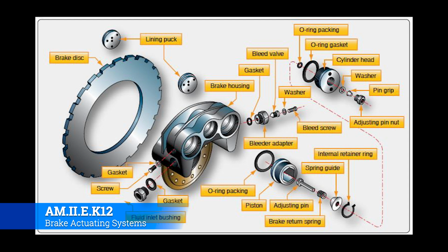So one of the things to look for when you have a dragging brake, if you're driving around or taxiing around and you hear a brake dragging, a lot of times that spring is off, or it's gotten stretched out or what have you. But yeah, it looks like there's a lot going on there. This is actually a very, very, very simple type of machine.